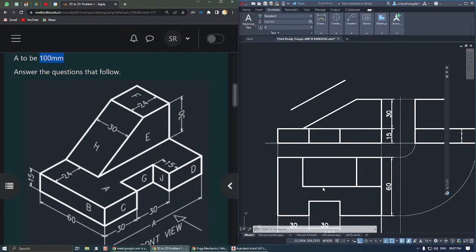Now coming to the true shape, what about these lines? These lines, are they the same length as they appear here? Yes, these lengths are also same, because you can see this is 30 and these lines are at 30 degrees on the left side. And when we see that object in the top view, they will appear exactly to be of same length. So this length is 30 itself, and same way we need 30 here in this direction.